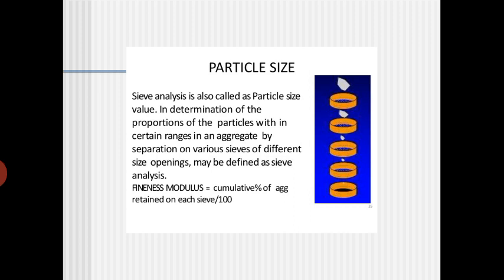its particle size. Normally for the cement, we calculate the surface area using this particle size. Even if you give 1 gram of cement, it will give the surface area, and based on that we calculate the particle size. The particle size of cement and the surface area are interlinked, and they are inversely proportional. If the particle size goes on increasing, the surface area of the cement decreases. If the particle size of the cement is decreasing, then the surface area goes on increasing. A similar concept is there here also.